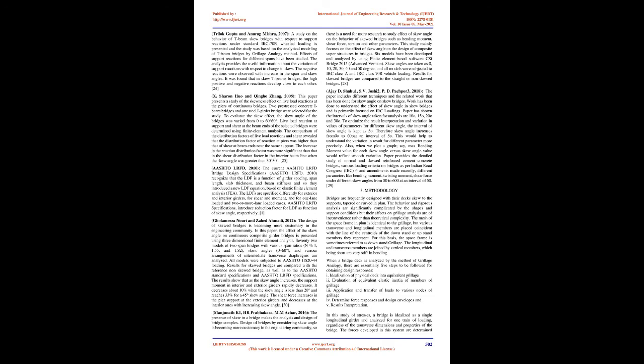6. Khaloo and Mirzabozorg, 2003. Using the finite element analysis method, FEA, analyzed 3D, simply supported, skewed bridges with different span lengths, skew angles, girder spacing, and arrangements of internal transverse diaphragms. It was concluded that load distribution factors of AASHTO standard specifications are up to 43.1% higher than those found by FEA. The authors suggested that girder live load distribution factors should be re-evaluated for skewed bridges.